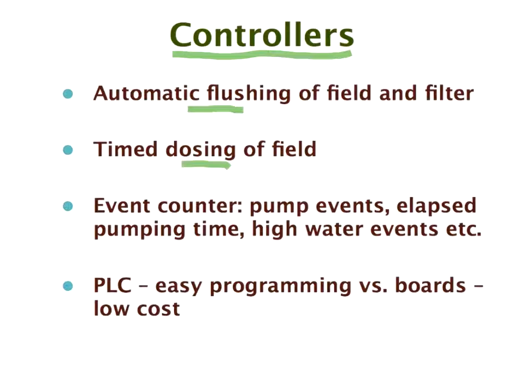You need to time dose your field. Now that is critical. Demand dosing is not a good idea with drip. In fact, it is a very bad idea with drip. If you remember, those who were here, I had that slide showing how the water moves away from the dripper when it's giving short doses. The maximum dose you'll ever want is 15 minutes of dose time. So say you've got a 1 gallon per hour dripper, you're putting out 1/4 of a gallon in 15 minutes. And then letting it rest.